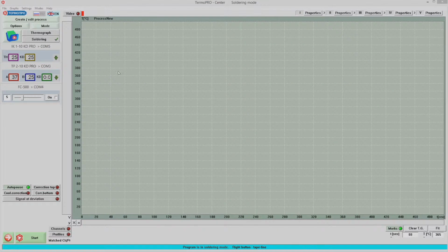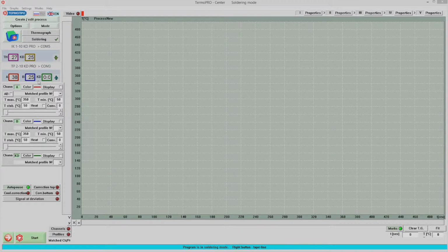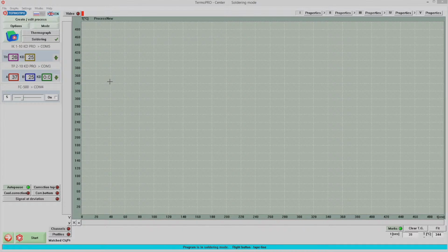When the NP3424AB Pro bottom heater is used, the function to synchronize its two heating plates is available. This option is helpful when operation turns from small to big boards. Changes in this function are made by check mark setting in the bottom heater panel menu.